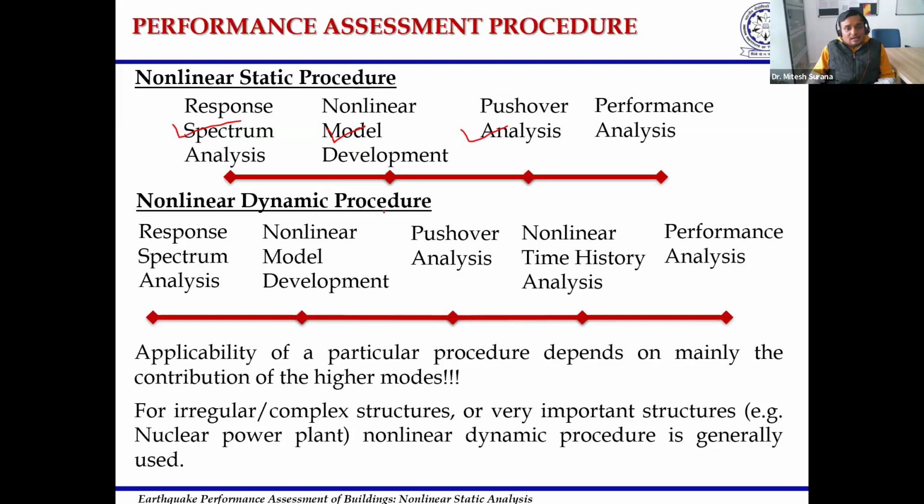In the nonlinear dynamic procedure also, I need to conduct first the response spectrum analysis to obtain the section sizes and reinforcement, then develop the nonlinear model, then develop the pushover, then perform the pushover analysis, then perform time history analysis, and then perform the performance analysis.